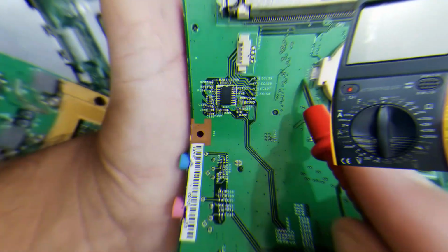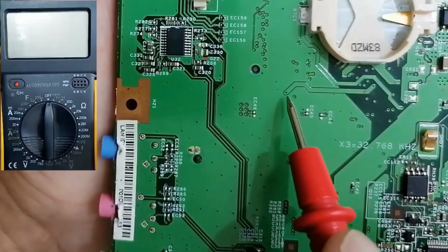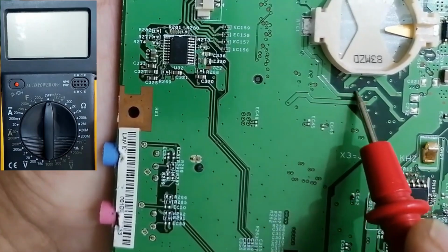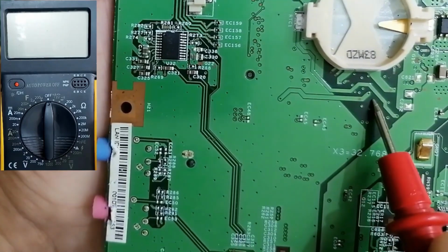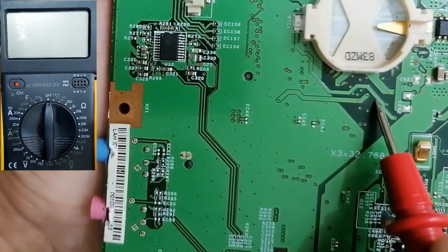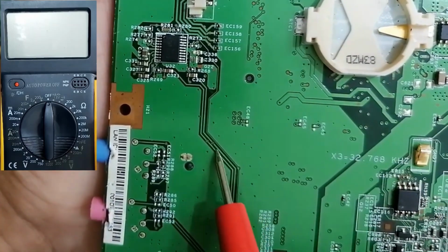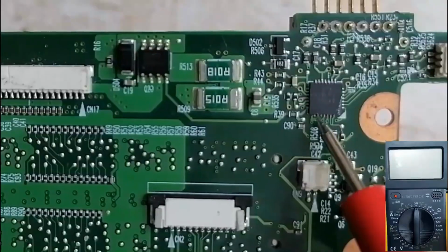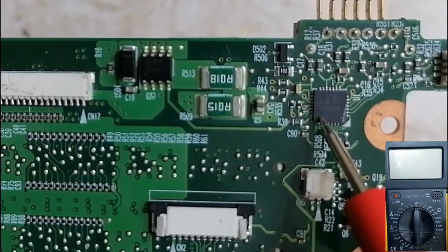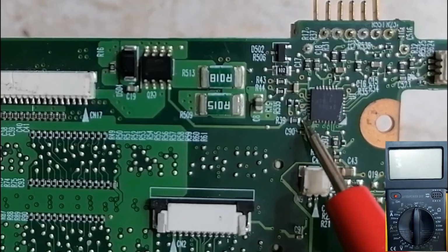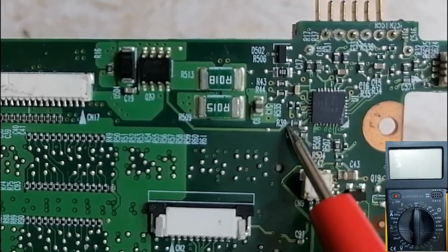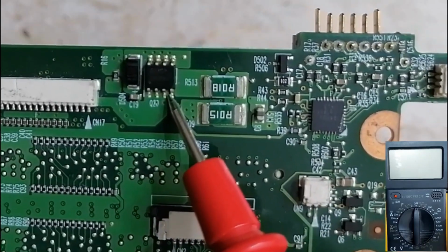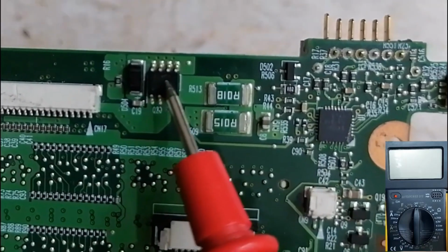This green area is for ground, but those bold or thick lines are for power, for voltage. It could be 19 volts, 5 volts, or even 3.3 volts. But these thin paths, as you can see, are for data. So the control signal is generated by this IC. Do you see here? It is generated here, passes through this resistor, and goes in this direction to the gate of this MOSFET. So this IC activates this MOSFET.